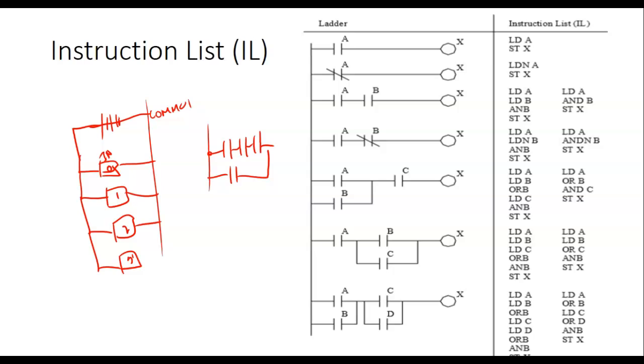So I've seen people do this, and then they'll try to come over here and do this on their input, and they come into the input of their PLC. But that's not the way it goes. What you do is you take one input hooked up to each port, and then when you write your program, you say, okay, when that button is pressed, this and this and this has to be pressed, or stuff like that. So we don't have series circuits. All we got is one output hooked to each output port, one input hooked up to each input bit. And then it's the program that determines how we're going to put the logic together.